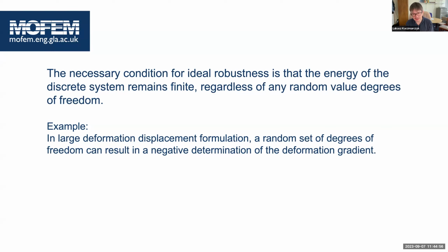So when you approximate the stretches, you can end up with that because the Newton method tries to converge, and sometimes it will go off tangent, and then it will go into the zone where you have interpenetration. It will generate a negative stretch. Your constitutive equation will blow up, and then you will have to restart the calculations from a smaller step. That is a big bottleneck when you are calculating, for example, impact.